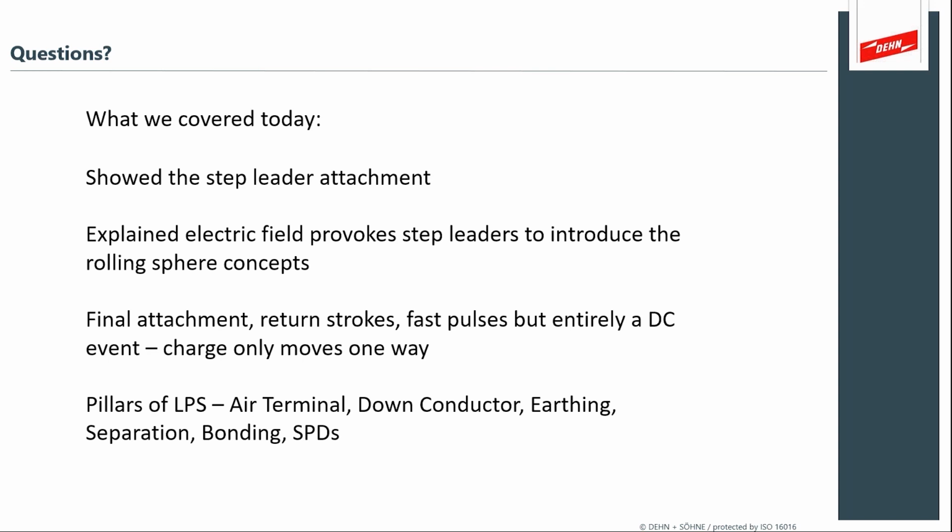Good question. Because what's intended is that the master ground bar at a facility is connected to the earth electrode in the ground. So you don't want to divert your lightning down conductor onto your master bar and then shunt it into earth. It needs to go to earth first. And the corollary to that comment is, you don't want to earth anything to that down conductor until it's buried.